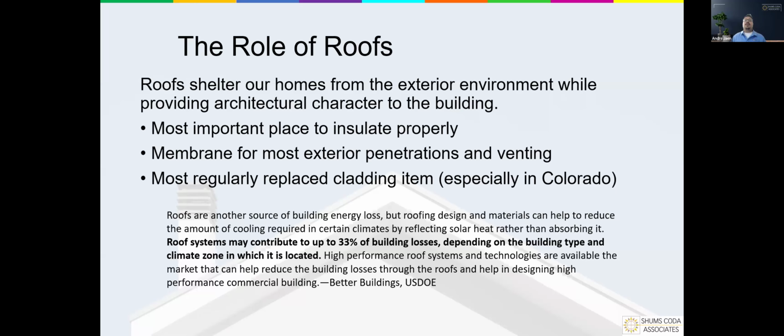It's also a membrane that we have to think about, right? It's in flux. It's getting pulled on by wind. It's getting pulled on by shear forces within the home, and shear forces transmitting their way up through that attic. It's also a membrane that's being penetrated very often. That is your plumbing pipes and vents. That can be solar PV. It can be chimneys. It can be ductwork and B venting specifically, right? Exhaust ductwork. It's a number of different things that pass through these assemblies. And then we also have desired penetrations as well, like skylights.